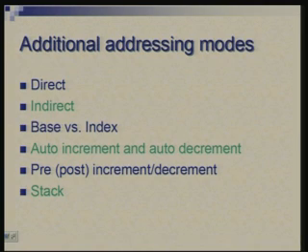Then stack addressing, which actually could be considered as a special case of auto increment and auto decrement. You are using a register to make a memory access, and also with every access you are incrementing or decrementing. So, there are processors which provide stack based addressing with auto increment and auto decrement.